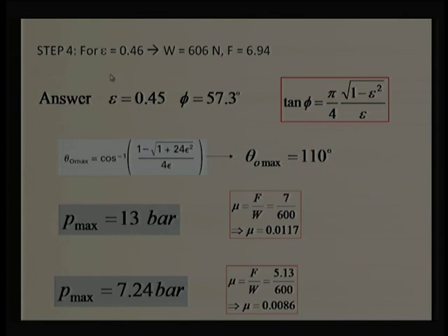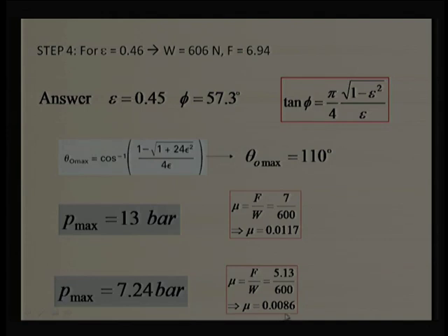First, the eccentricity is going down; we say that 0.5 may be recommended, fine, but the larger length is increasing the maximum pressure. The smaller length gives smaller pressure compared to the larger length, which is quite the reverse of expectation. And the coefficient of friction for the smaller length is lesser than for the larger length.